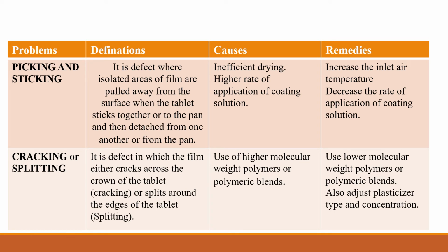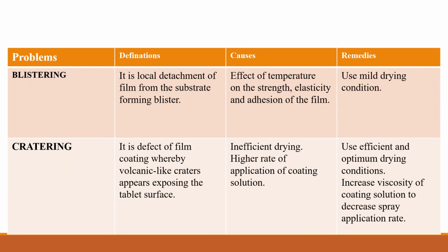Next, how can it be minimized? It can be minimized by using lower molecular weight polymers or polymeric blends, and also we need to adjust plasticizer types and concentration.